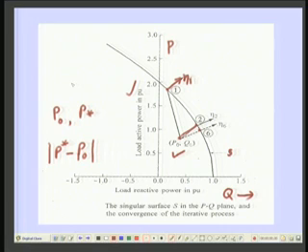In the multi machine system we denote the loading condition in terms of initial P and Q through a parameter, and we find the final as rho star. This rho star lies on the hypersurface which represents the unstable operating condition.